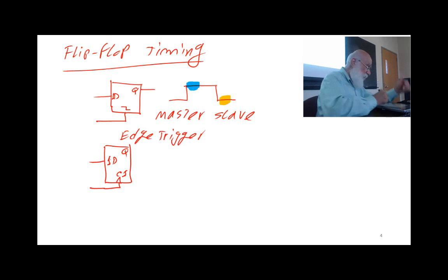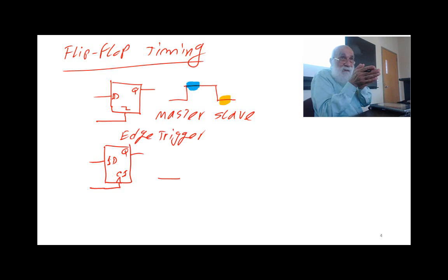Whether it's rising edge or falling edge doesn't really matter, but the key thing was that both taking of the inputs and putting it half in the middle is done as the clock is making a transition from 0 to 1, and as the clock is making a transition from 0 to 1, the other half is also becoming active. Actually, the two things that I'm showing here happening on two levels of the clock, in the edge trigger, they happen on the same edge of the flip-flop.